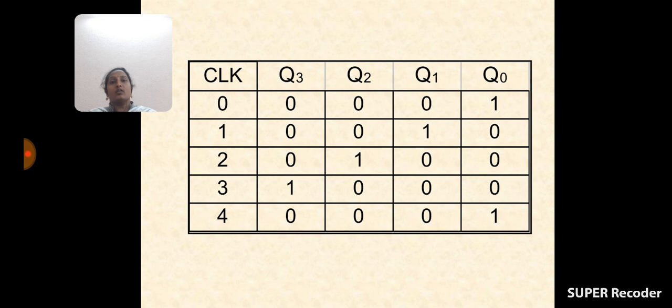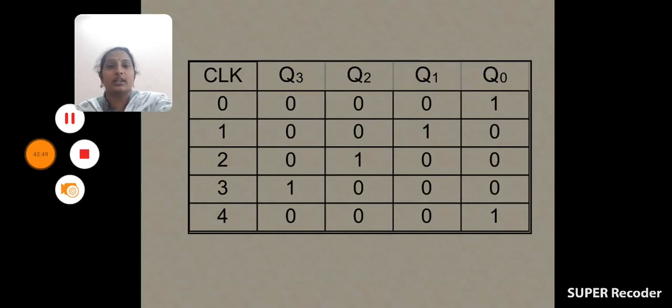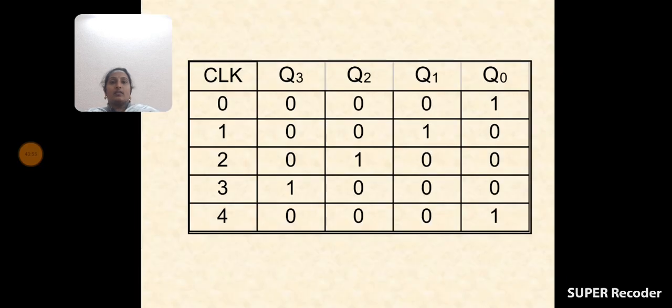The counting is started from bit 1. Each and every flip-flop has bit 1 at some stage. So here for the first clock pulse, preset is applied to the first flip-flop, so that bit Q0 becomes 1. So the series 0 0 0 is not there at any time. That is the main advantage of this ring counter. And here it is a synchronous ring counter.